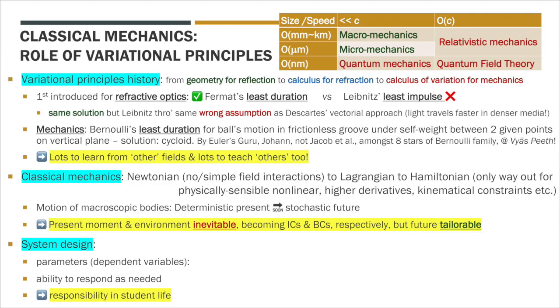How do you solve for them? Now the ability to respond as needed becomes the critical thing. That's basically where smart structures or adaptive structures come in. The whole idea of smart or adaptive structures is that now you have an ability to sense what the environment is, and based on the sensor we supply a feedback to the actuators to actuate in such a way that you're now changing your basic system characteristics in order to cater to the new environment, the changed environment.